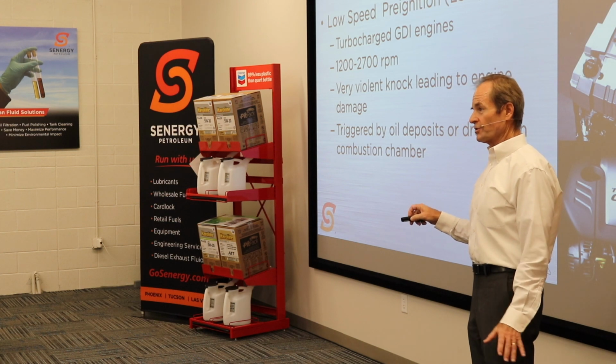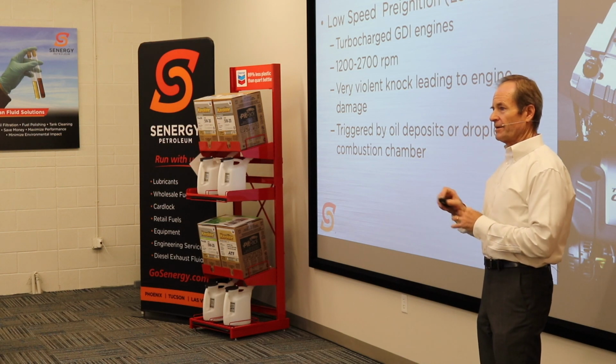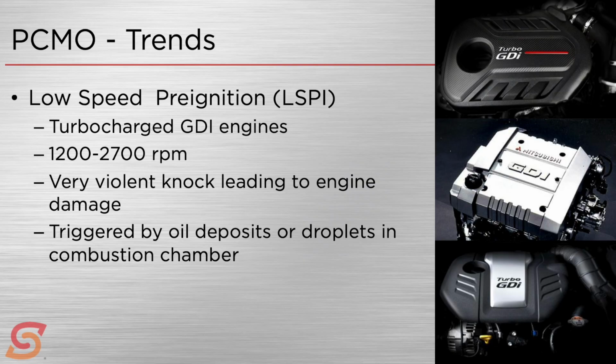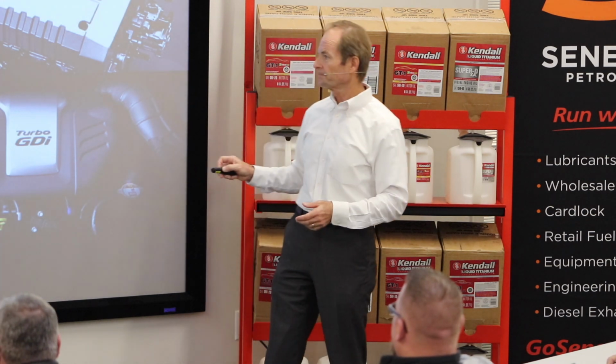So far, all the research, there was a lot of research done to figure out the why. It looks like it's triggered by deposits and or oil droplets remaining in the combustion chamber. Okay? So once they determined that, they worked with reformulating oils and found out they could formulate oils that would get rid of LSPI. Okay, so that some oils would cause it, some oils wouldn't. And the engine oil, obviously you're an OEM, you're making these engines, putting them out on the market, and you got warranties to worry about. This LSPI stuff would be pretty important.